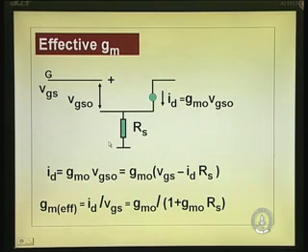through that, from the drain to the source through the resistance. So, that is why VGS0 is the total voltage VGS minus ID times RS, minus this drop. So, that is what is put here. Now, actually what you do is make rearrangements, and ID times 1 plus GM0 times RS equals this quantity, GM0 times VGS. Transconductance in the real device is ID divided by the applied voltage. This is a small signal voltage, not DC, incremental quantities.